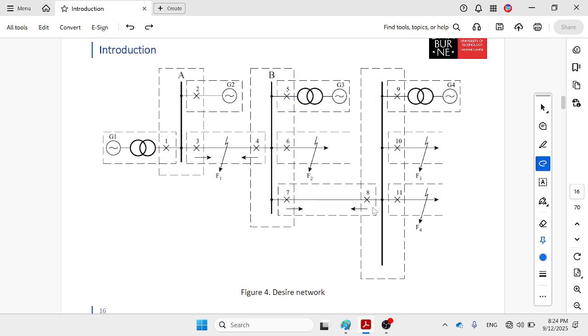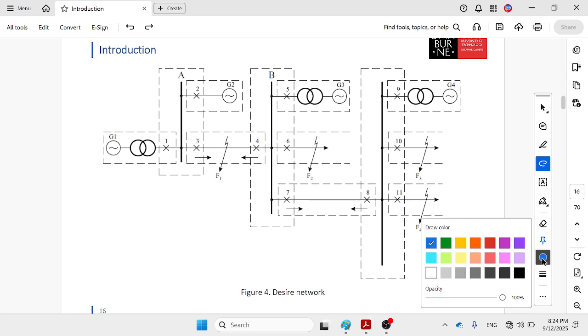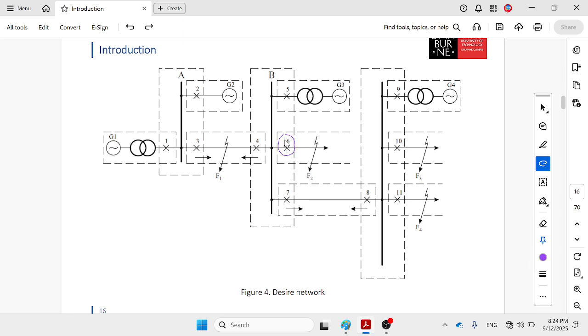Okay, let's consider the next case, which is number 6. For number 6, the primary relay, of course, is number 6, meaning a fault at point 2. Of course, this is primary. Which one is the backup? Okay, if number 6 fails, if it's not working, we have a source of energy sending current to this point. So number 5 is the first backup. From this way also, we have two sources, 1, correct, and 1.